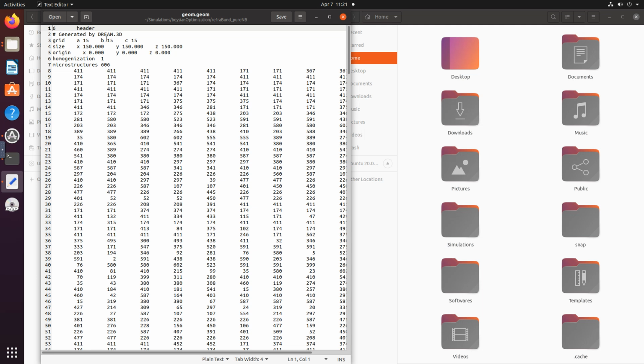They are not fully resolved because I am only interested in looking at the global results. I'm not interested in looking at the local results. We have published research papers in the past about this technique. We have shown that if you want to run global simulations, you just want to calibrate your data, all you need to do is run simulations of this small RVE that has a lot of grains, whose orientation is representative of your material, and whose phase composition is also representative of your material. If you calibrate your parameters based on that, you will get reasonable results.